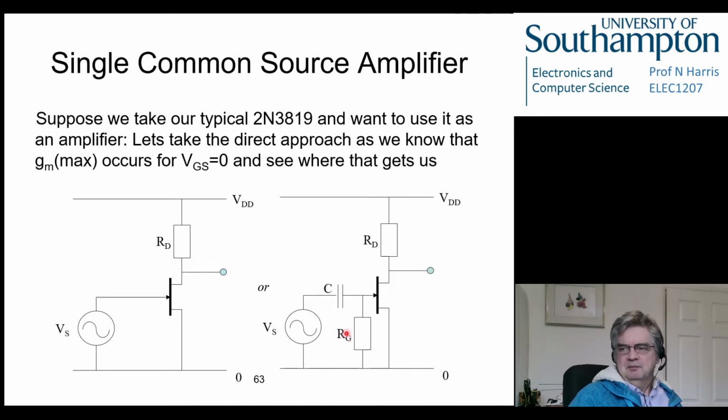And this means, because no current is flowing into this thing here, that both of these must be at the same potential. This end is tied to 0, therefore this end must also be tied to 0. So we've sort of biased it at 0 with a huge great resistor here, and with no current flowing through it. So it's just pulled it to that point. This is called a pull down resistor. So now any signal coming through here will superimpose itself on top of this signal. Won't want to go down here because it's used a big resistor, and so we have a signal superimposed on 0. So we've effectively biased it that way. We'll talk a little bit more about biasing as we go forward, because this is quite a neat little trick, really.